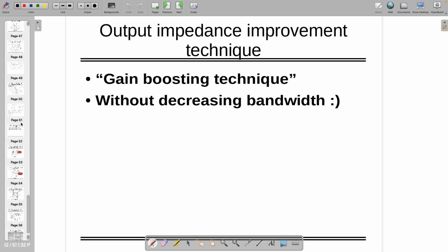Okay. So now, how to improve? We are more greedy. We understand cascode is one technique through which you can get good Z out and have the required V out also. V out you can achieve as low as 2 VDS. This is the best thing we could have tried. Even with depleted mode transistors, we could have achieved only this. But we are more greedy and we want a better current source whose Z out is higher and having lesser and lesser V min.